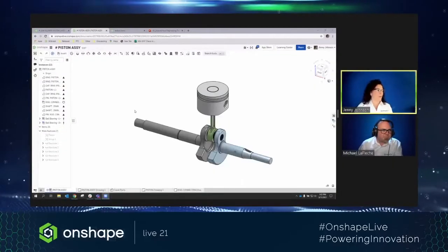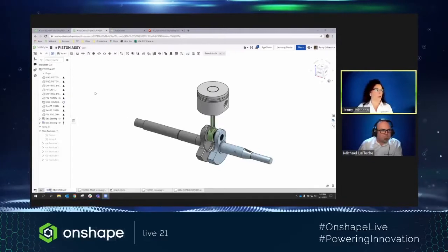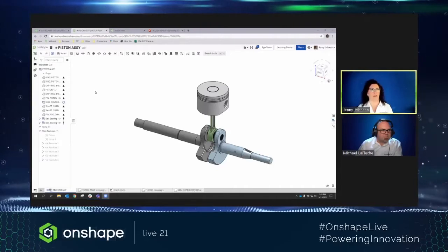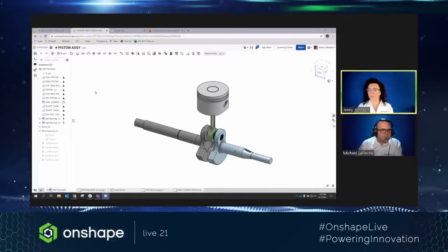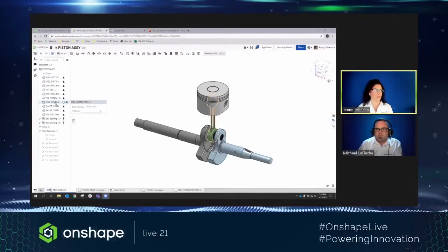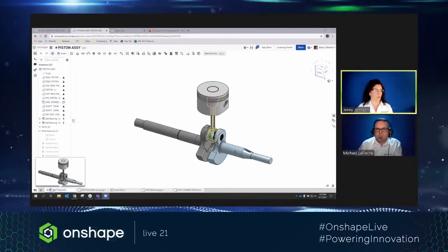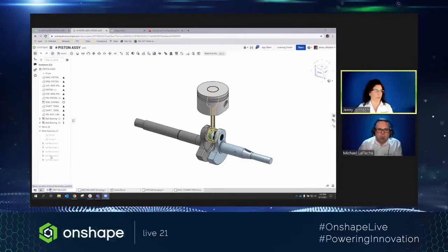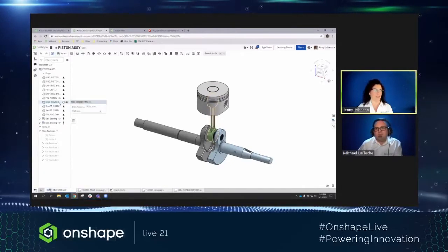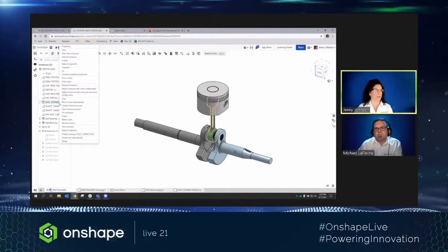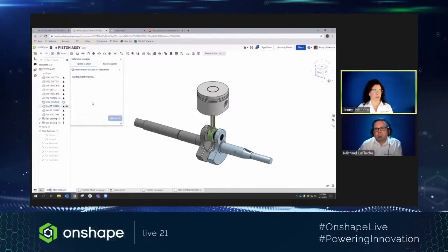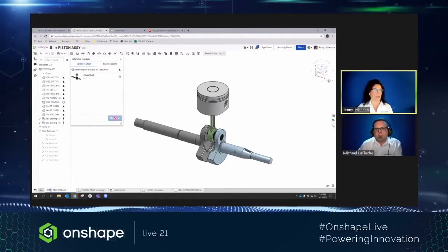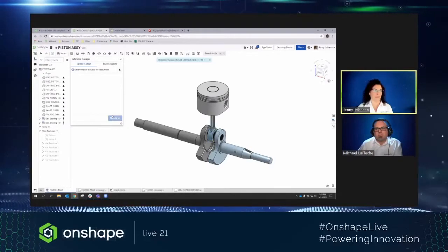So now that Mike has done that release, a lot of the confusion, if you've come from a traditional PDM kind of environment, is how do you make sure that that's being used? When I come back into my assembly, I will see, even before I come into this tab, that there's an update pending on this tab for the assembly and which documents need to be updated, so that I can come in here and update this document. So I want to go to that new version. It knows it's going from C to F. I can update all of them and we're good to go.